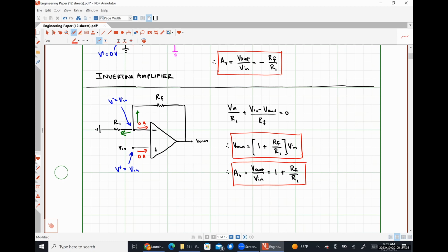So how many of you guys know what a piezoelectric crystal is? One person. How many of your parents have a gas grill that has a push button ignition? Exactly right. So that is a piezoelectric spark generator. Effectively, when that crystal mechanically deforms, it creates a large voltage. However, just because it's capable of creating a large voltage, enough to literally cause arcing and light a grill on fire, does not mean it can produce a particularly large amount of current. Actually, the current produced is extremely small.